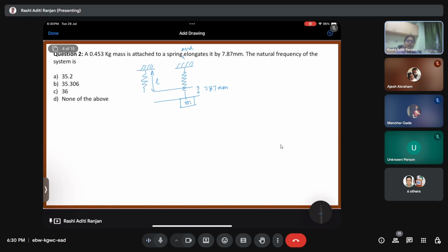But this is an ideal case that we are talking about. So let us say that it is at an equilibrium with a spring only. We don't know about the intermediate step as of now because we are just concerned about the natural frequency, and the natural frequency does not depend upon the damping value. The damping value is only going to control how much transient we are going to see, up till what time the oscillation is going to happen.